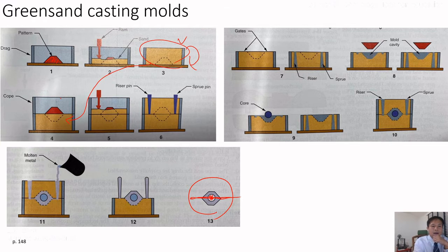This is because in general, this kind of shape, we cannot make in one shot using the sand, because in the first part, after we put the sand, we push this top area to make a sturdy sand structure to stick to this actual material.